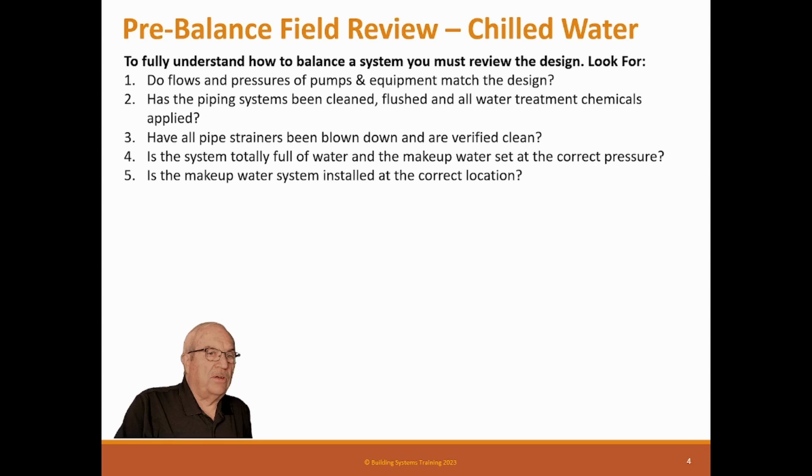Is the makeup water system installed at the correct location? Where do they have the makeup water? It needs to be at the suction of the pumps. If it's not near the suction of the pumps, then your system will not work correctly.